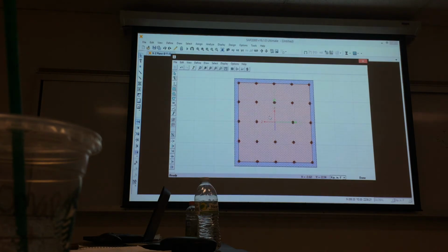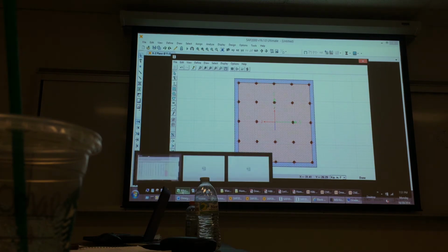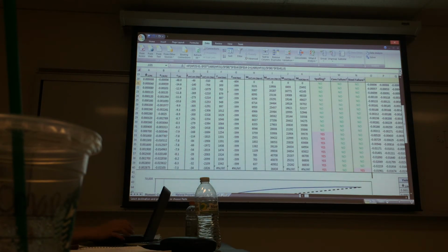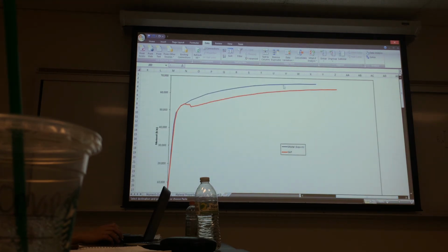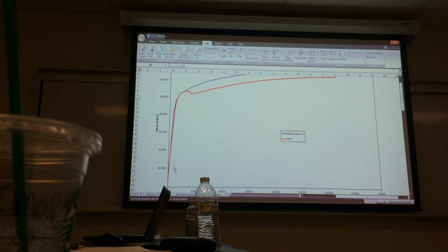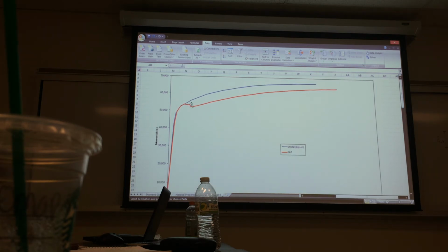So if we want to compare this with our results, have that middle plot over here. See, they're actually pretty similar between SAP and our hand calc. So I didn't do any parameter studies on this in terms of looking at, is my mesh appropriate or not? But you'd ideally want to do that. And what you can see is, essentially for the very beginning of the curve, these guys are matching identically. We just have that little bit of a difference in how it's solving things from the modeling point of view. But after that, essentially, it just follows our curve pretty close.